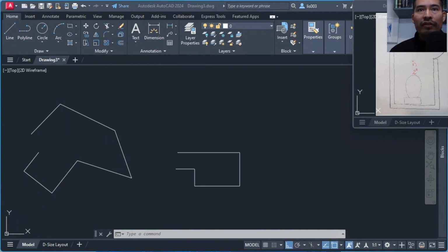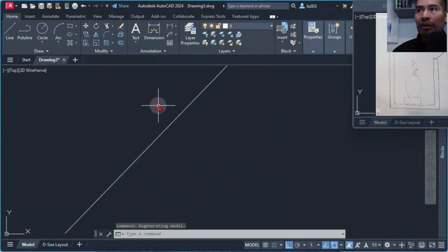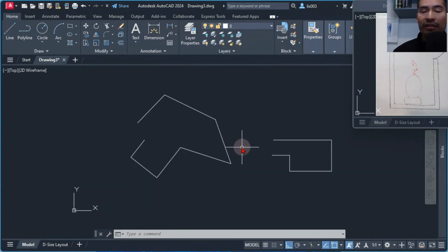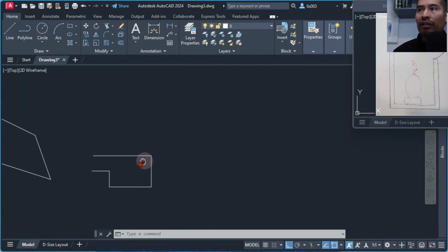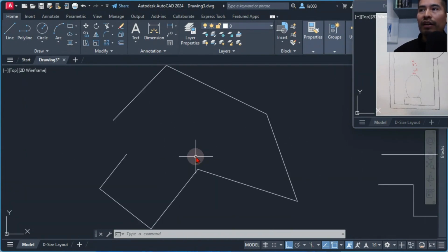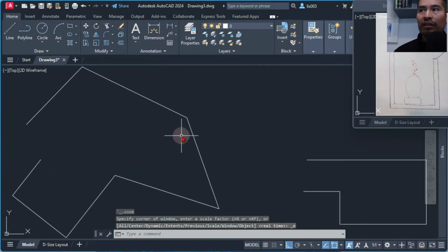All right, now let's learn how to navigate in AutoCAD, how to move yourself inside the program. To zoom in or out, we can scroll our middle mouse wheel like so to get closer to our items. To pan, we can simply hold the middle mouse wheel, click and hold it like so, so you can pan and locate your items quickly in AutoCAD. Finally, to zoom extents into your entire drawing, we can double click on the middle mouse wheel like so.